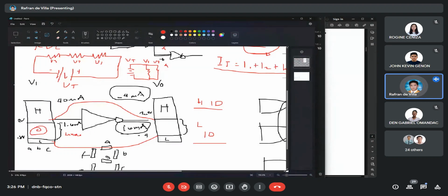But of course, take note, 10 inverters connected to the output of this single inverter is already heavy. So we use the smaller value. Probably you can give a leeway of 25%. So a maximum of 7 inputs connected to the inverter output. Because if you connect all of them, its output is a maximum of 60 milliamps, and it is dangerous, it may overload.